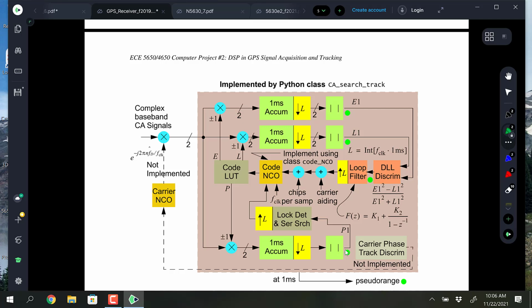So the way you do the acquisition and then the tracking is you have the on-time correlator, the bottom one, which is the one that's trying to see the course acquisition. And again, this would be repeated. You'd have many more correlators in a modern receiver, but this was just to keep it simple, just 3 correlators. So the bottom correlator there is just looking to detect lock, seeing that you've risen up on that triangle correlation peak high enough that you're saying stop stepping the code. So here the code NCO, numerically controlled oscillator, is getting stepped to do a serial search, but once you detect lock, then you stop stepping the code, and then these 2 detectors or correlators, one's running early, one's running late, so it can estimate essentially the derivative to decide which direction I need to tune the code offset in to pull it exactly into lock.